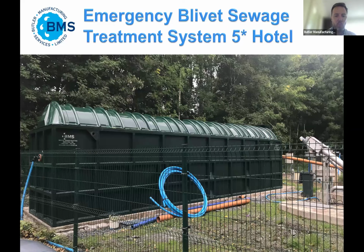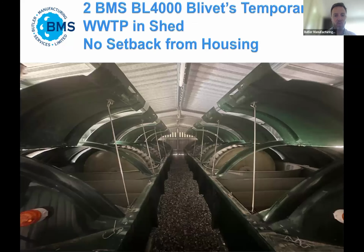This was a project we did in Ireland where an SBR system was failing and the hotel was going to be closed down. So we put in a temporary BL4000 Blivet, which is 500 population equivalents, to take over the excess load in the plant. And within a year, this was integrated into a brand new Blivet packaged sewage treatment plant. So temporary sewage treatment for overloaded plants, if there's a temporary excess load, is a very viable solution too.